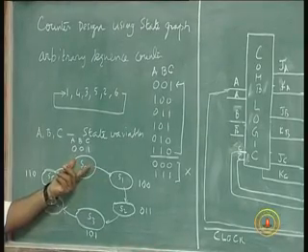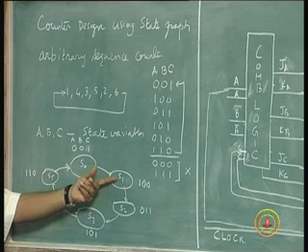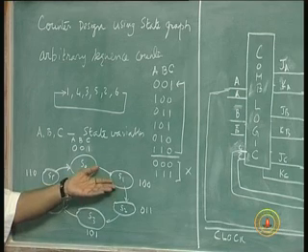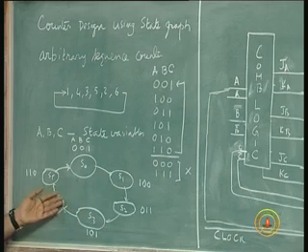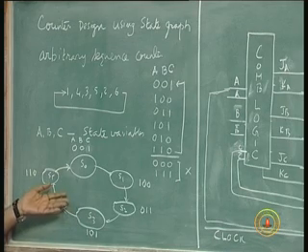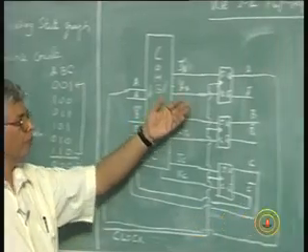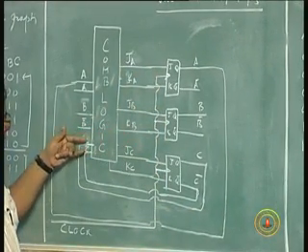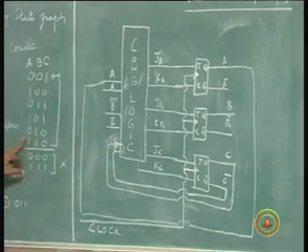So, what we have to decide is, from this state to this state transition, what inputs should be given to the flip flops. There are 6 states, so it requires a maximum of 3 flip flops. With 3 flip flops, you can have 8 states, and these 3 flip flops have to be steered from state to state based on the present state values and the sequence required.